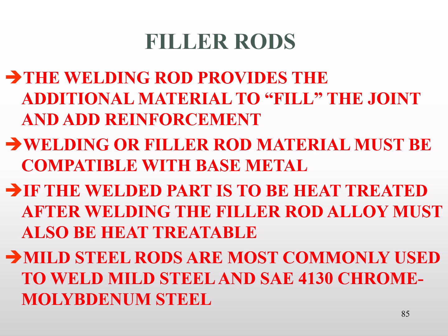The biggest key factor and the biggest question that comes about filler rods is, what's the most important characteristic when selecting a filler rod? Well, the most important is it must be compatible with the base material that we're welding. If it's not compatible with the base material, your weld will be corrupt, it'll be a bad weld and a weak weld, so everything else won't matter. And if the part does have to be heat treated after the weld, the filler material must also be of a type that'll accept that heat treatment and harden along with the part.